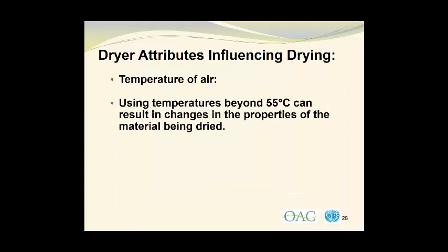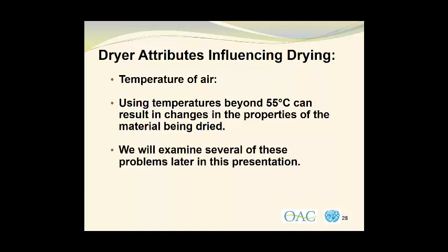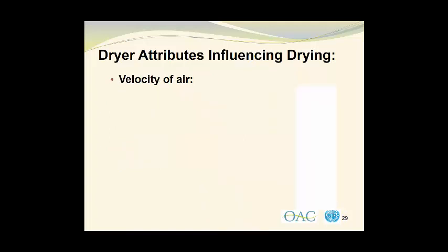Using temperatures beyond 55 degrees Celsius can result in changes in the properties of the material being dried. We will examine several of these problems later in the presentation. So please exercise caution and do not be tempted to go to elevated temperatures that are in the area of 60 degrees Celsius and beyond. Please try to confine your drying efforts to 50 to 55 degrees Celsius.